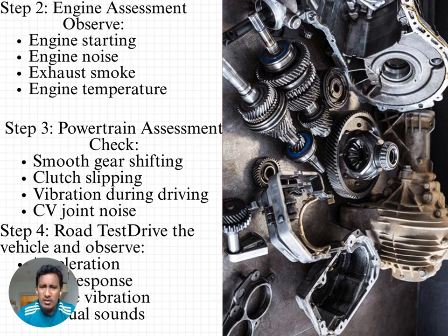And we can also inspect or assess the powertrain. We can check the smooth gear shifting, clutch slipping, vibration during driving, and CV joint noise, which is very important. We can assess those checks and parts very easily by our visual inspection, and we can easily identify if there is any problem at that moment.